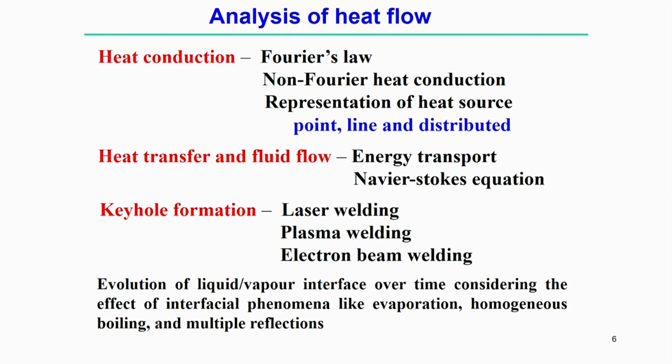But when you use very highly concentrated heat, specifically in laser welding or electron beam welding, there is a formation of the keyhole. So we need to consider the keyhole effect, and then we can improve the simulation and the temperature distribution results.